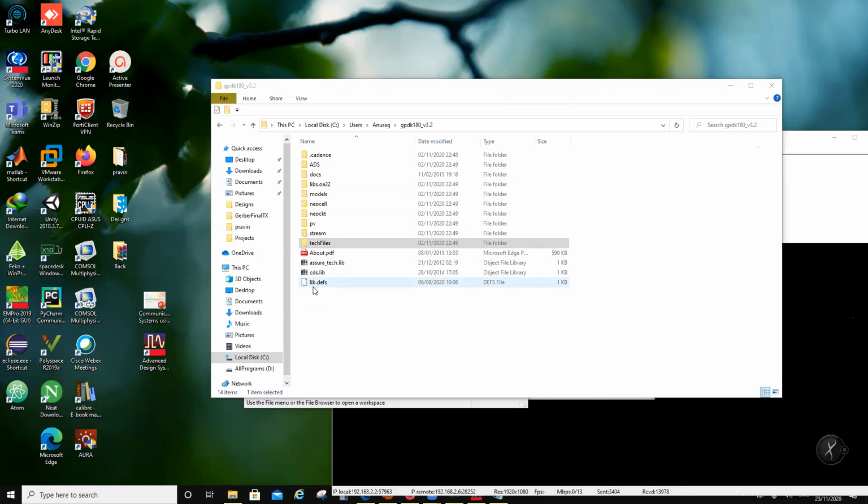So there is nothing which will stop you. Now, why did I still stick to this GPDK? The reason is it allows you to do the layouts, the layers, the via layers and the metal layers and stuff like that. Then there are thermal models in this. So I wanted to make a kit which can be used by everyone. There is no restriction.